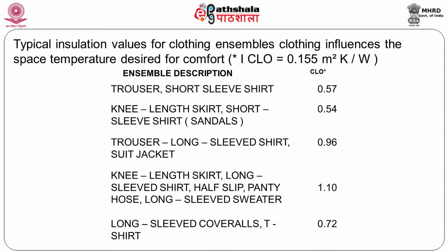Now here again, when we talk of 24 degrees as being comfort, what is allowed for is a clothing level of 1, which means a light business suit. I am today in front of you underclothed. If I put on a jacket, I can still be comfortable at 24.